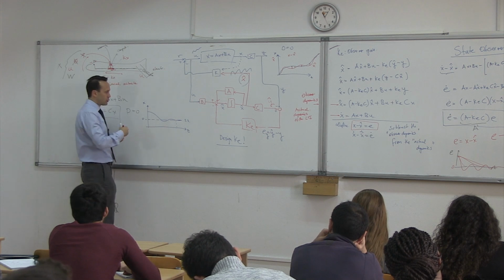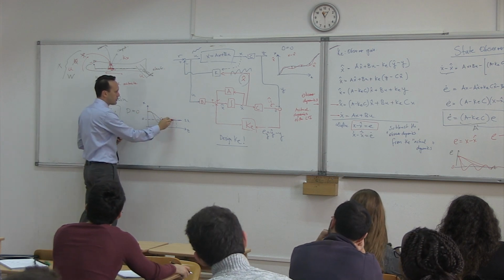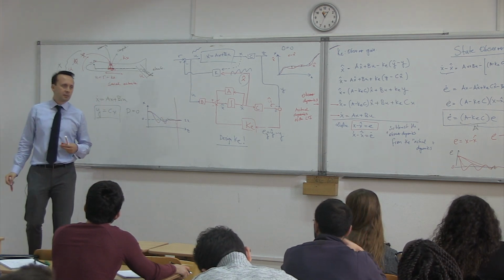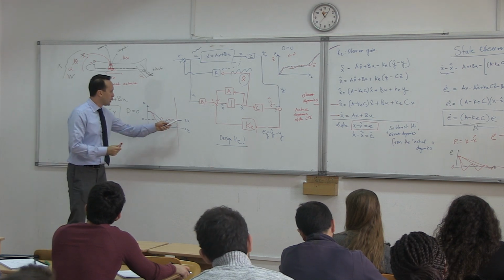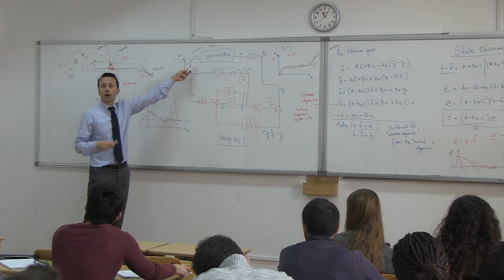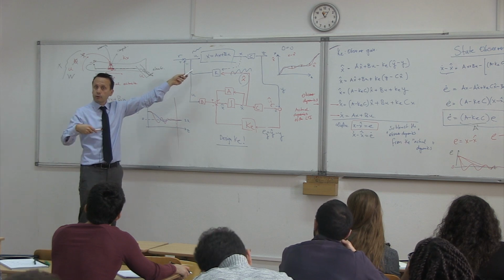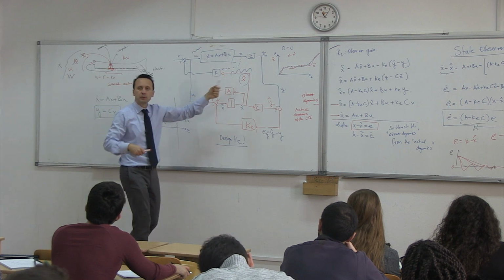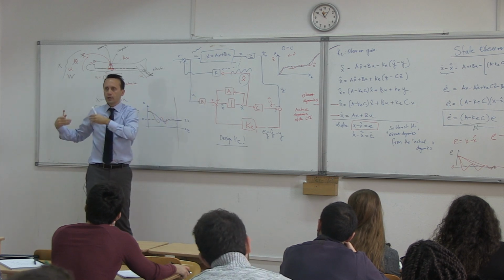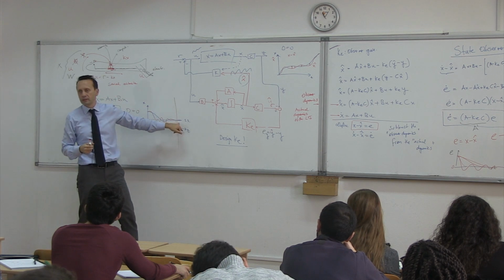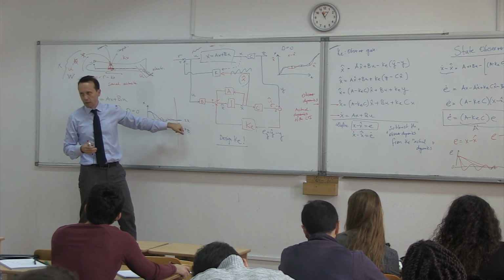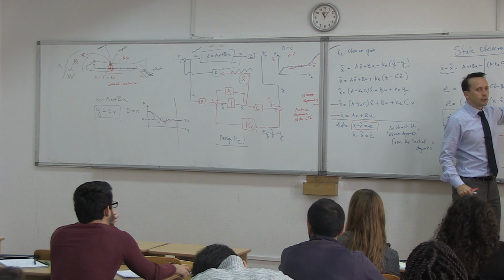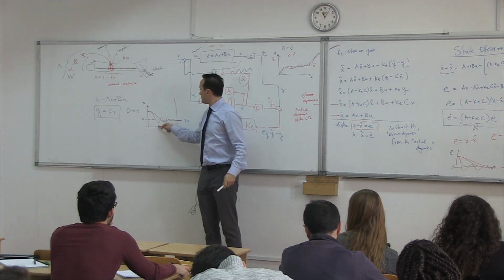Okay? With a bad observer, you might be doing this. They both converge about the same time because the eigenvalues of the closed loop are at the same place, and the eigenvalues of the observer dynamics is faster anyway. So the error of x hat will die ahead of time anyway. So at the end, the closed loop will all match at the same point. Okay? So even if you do have oscillations over here, you will probably see it in the transient, but not at the end.